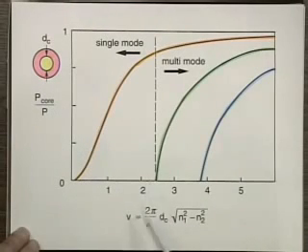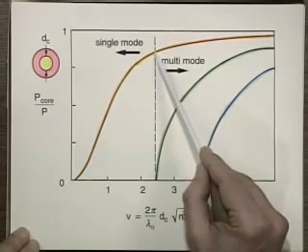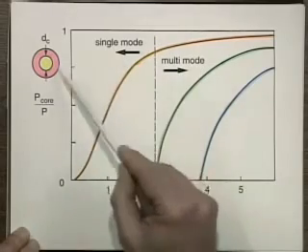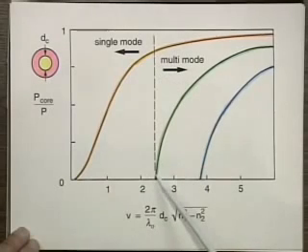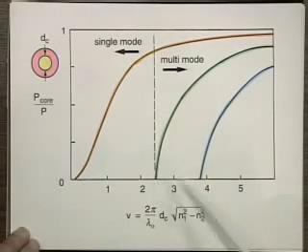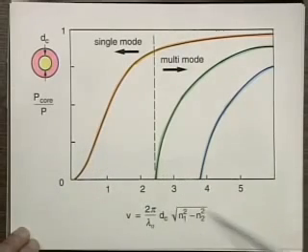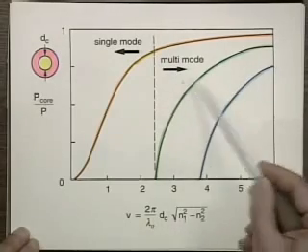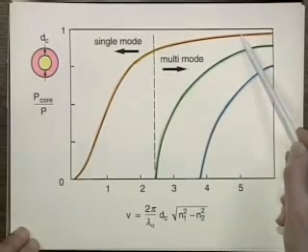And as I approach the multi-mode operation, the single mode travels, let's say, about 80% or so in the core, but not in the cladding. Now, when the onset of multi-modes comes about, then the multi-mode will propagate mostly in the cladding first, more in the cladding than in the core, and then as I increase the V number, they again will start propagating in the core, and their index starts to approach the index of the single mode.